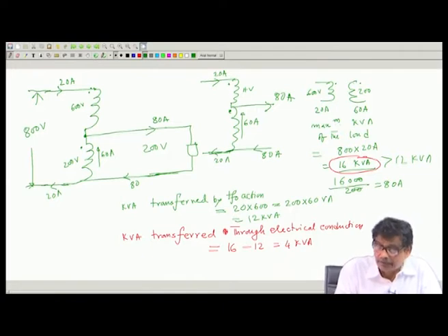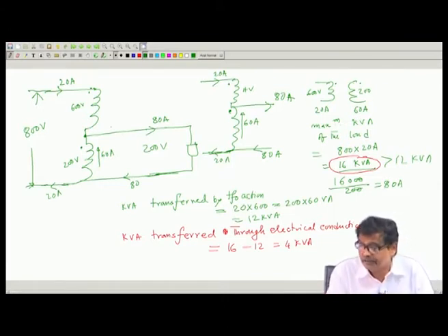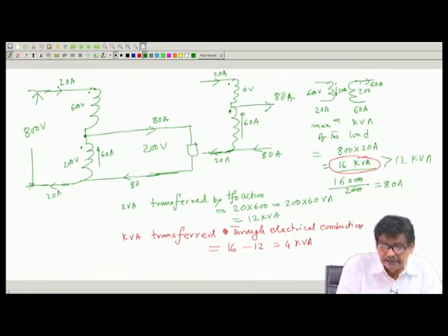See, when you connect a two winding transformer in auto transformer form, the primary and secondary winding are really unaware of the fact that you have connected them in this manner, unlike a two winding transformer. It only knows this much, that if it has to deliver 60 ampere through the dots here, 20 ampere must come in. That is its duty. Voltages are rated voltages, and based on that all the calculations go.